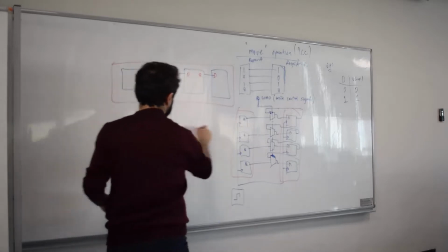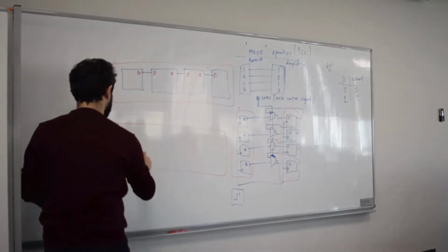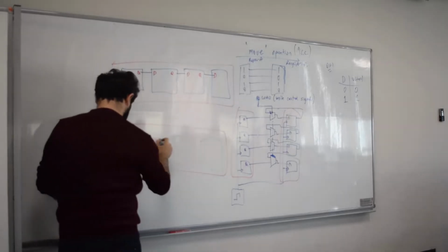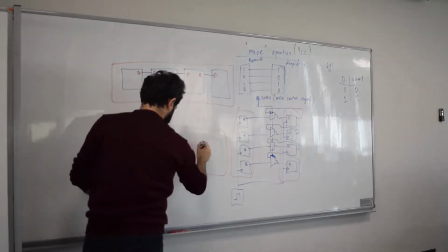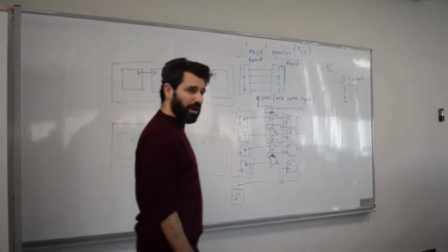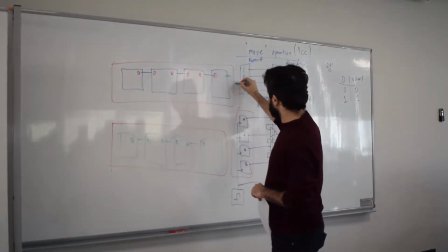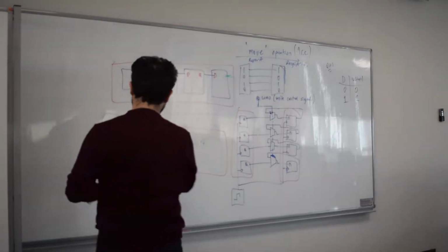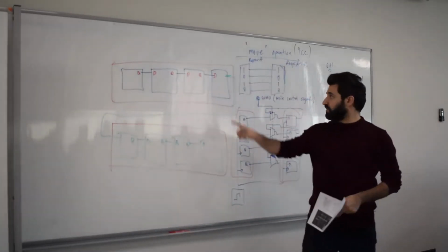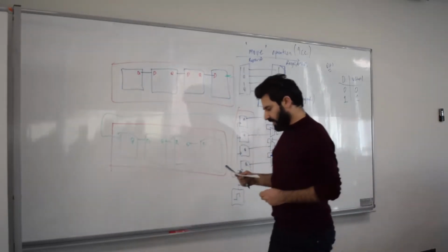I've got another register here, correct? Let me use green. I have 1, 2, 3, and 4, with QD, QD, and QD, and I connect them as well. Now, what I would like to do is basically put this output to the input of this D. Okay? So that's how we connect them. You see, it's a serial connection. It's a single wire. It goes into here.